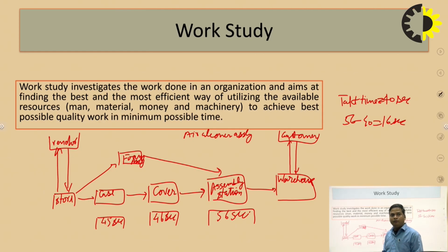We can bring the case injection molding machine, the cover injection molding machine, and the foam assembly, which are placed randomly in the plant, to one place, along with the assembly station, so that the traveling distance and the number of workers on these stations can be minimized, and the cycle time can also be minimized. This way we can improve a particular machine, and we can also reduce WIP, work in process inventory.